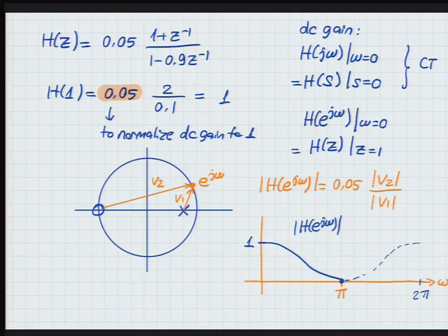Can I put poles on the unit circle? No, that's the problem. That causes instability. But zeros don't affect stability at all. They are irrelevant to stability. So it's okay to have a 0, and when we're designing simple filters, we can use that fact. If there's a frequency that we really want to kill, like pi in this case, we can put a 0 exactly on the unit circle at e to the j that frequency, in this case, e to the j pi. So if I'm designing a general low-pass filter, I don't need to mess with that 0. I think it's fine where it is.